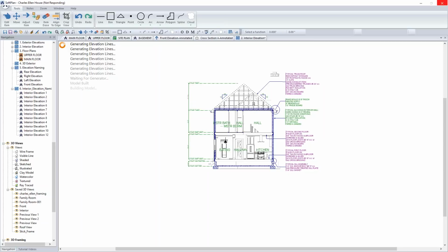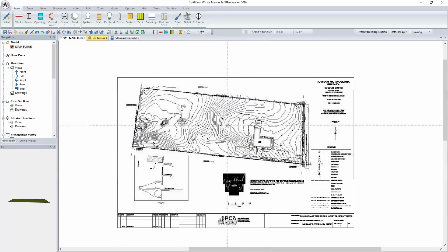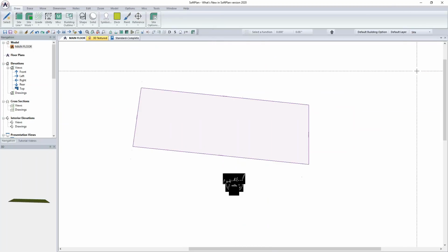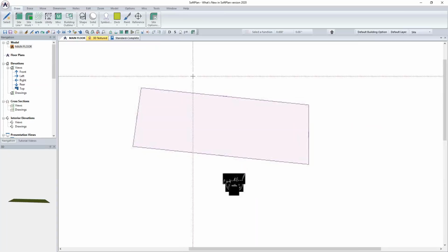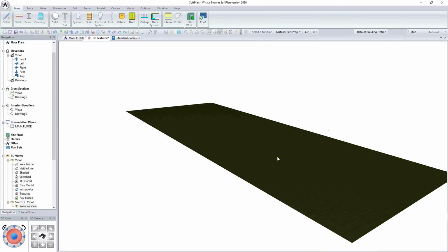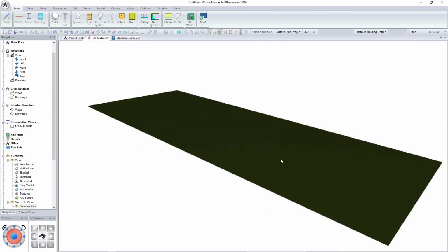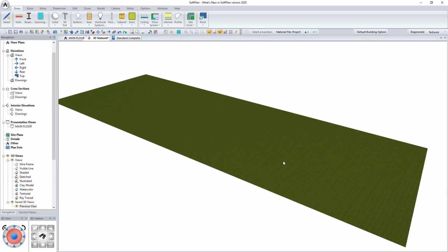This is an actual project that I'm working on, and so I'm going to be pulling up the engineered site plan drawing for a second, and then I've converted it. So this is the stamp drawing at this stage. And as I move into site plan, I've basically just gone in and traced the outline of the site. Now that's something you do if you want to create a 3D model. And of course, when you do that, your site is now flat, right? And once you've got that site in there, you would then go in and add your topography.